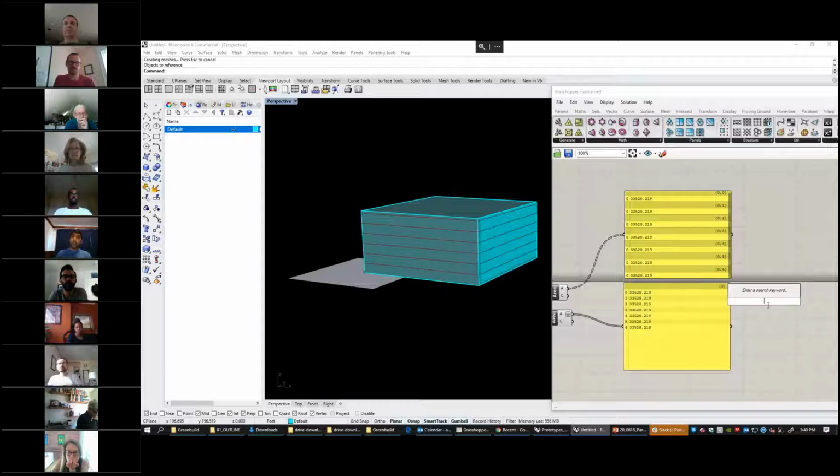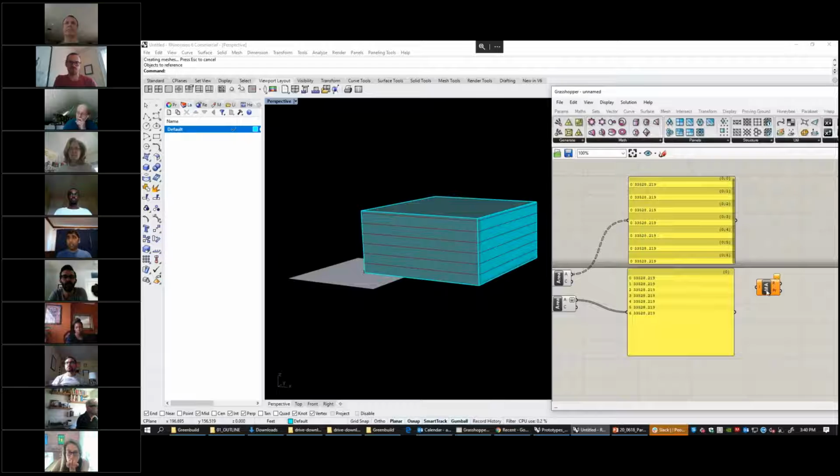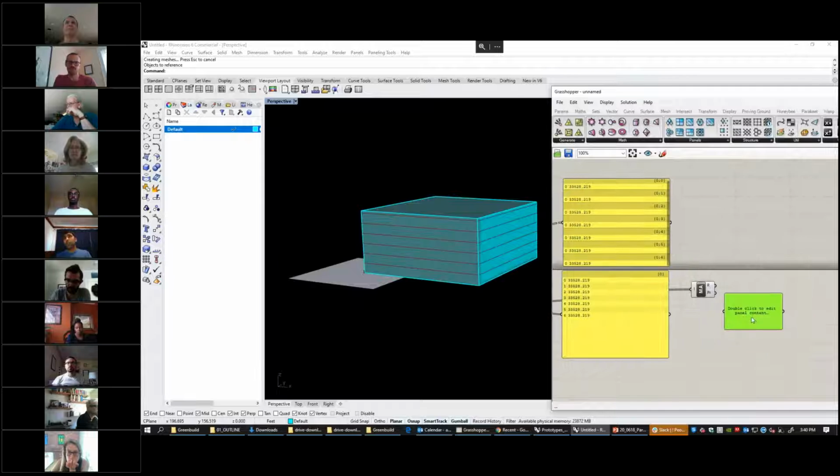And then there's also another thing called mass addition. If you have a list that's flat and you want to add all the numbers in that list together, you can plug it into the mass addition and get the result. So you can say, oh, all 7 of these floors together are 234,690 square feet. So if you have a mass, you want to get your floor to floor heights and get your area, that's a quick way to immediately get that number out.